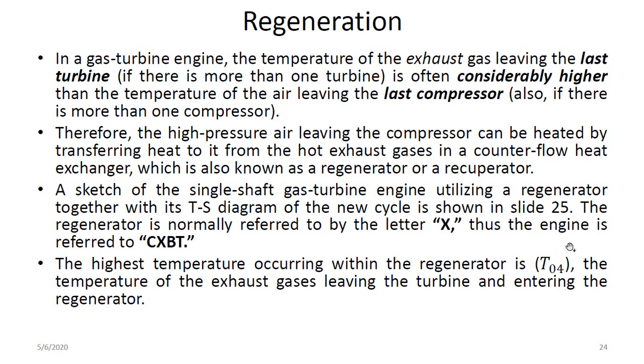So to avoid that wastage, you can do the following. The higher pressure air leaving the compressor can be heated by transferring heat to it from the hot exhaust. So for this hot exhaust which is leaving, you can make a bypass duct to heat the air that is leaving the compressor in a counterflow heat exchanger.